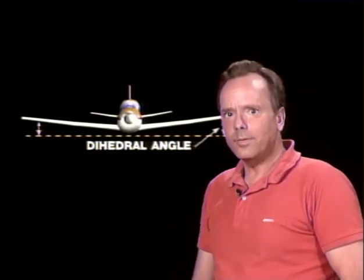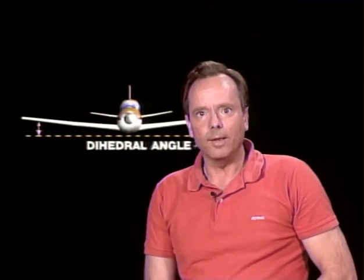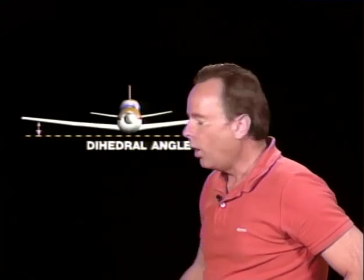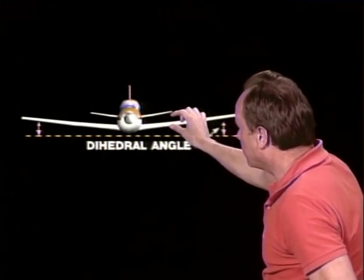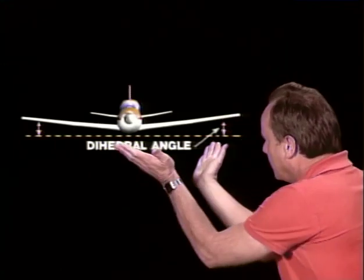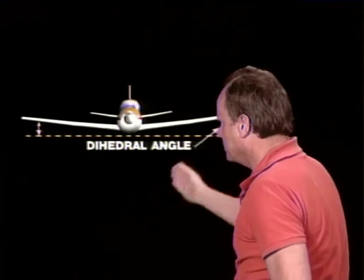They're going to ask you on the test, how do you measure that dihedral angle of a wing? One way to do it is place a straight edge and level protractor on the front spar of the wing, and you can measure the dihedral angle of the wing. Another way is to use a dihedral board and bubble level along the front spar of each wing. So those are two ways to measure the dihedral angle.